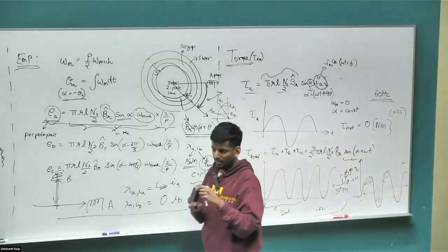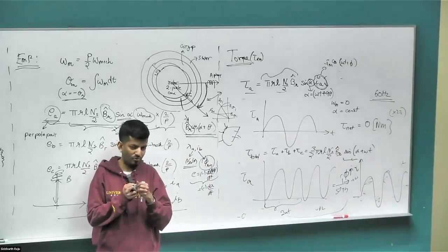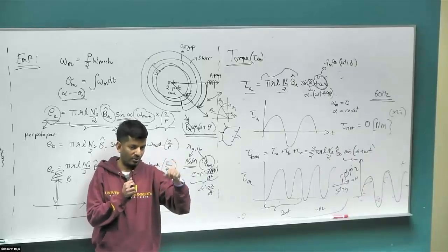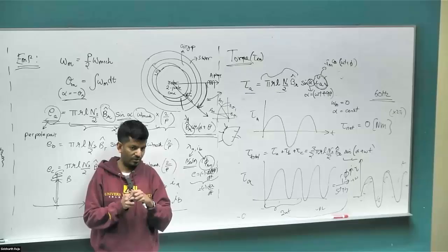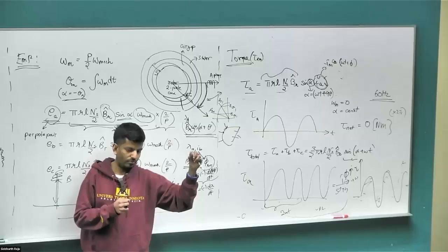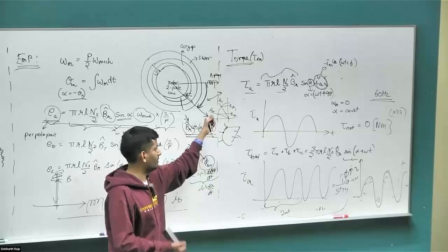Has anybody seen a one-phase permanent magnet synchronous generator? Most of you might, without even realizing it. How many of you have been to Harbor Freight Tools? Whenever you go there, they have this section for camping generators, where it's just a one-phase generator and there's a single-phase outlet that comes out of it. So it's basically a permanent magnet synchronous machine with the generator part coupled on the mechanical side, and the outlet is basically the A-phase terminal that's coming out.